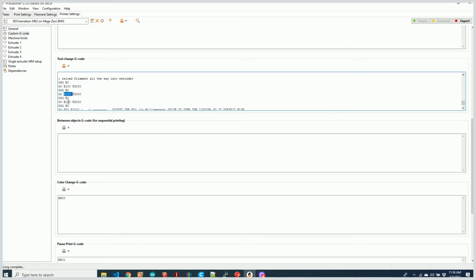This is going to load 350 millimeters, and you're going to adjust this last value to get it to right where your nozzle is, right? You're going to increase it or decrease it. We went 380 before because that ensures that we've pushed it past the extruder as far as we can go, and we went 30 millimeters extra. But in reality, you don't want to load 30 millimeters extra because then you're going to be squirting out filament. And you're going to adjust this value to compensate for that. Just going to dial it up or down to match exactly what your length is.